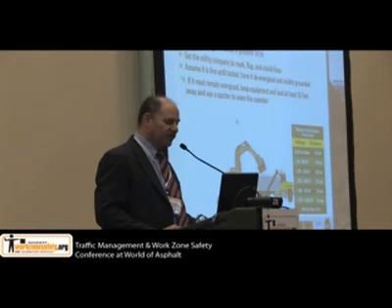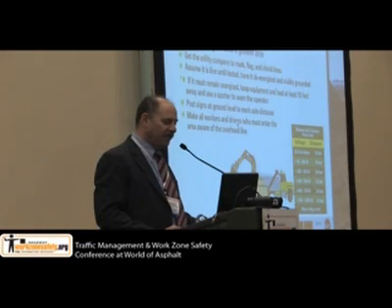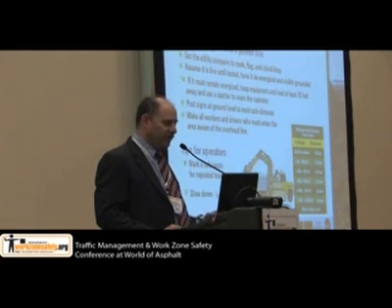If it is energized, keep equipment and loads at least 10 feet away and post signs at the ground level to mark safe distances. Make all the workers and drivers who are entering the area aware of the overhead power line, have the operators follow a safe route for travel, and make sure that they drive slowly.